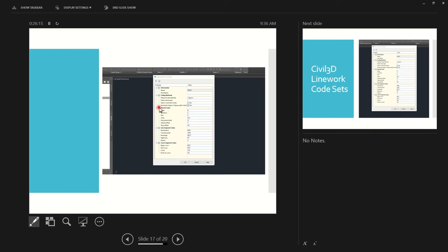But if I look at the special codes, this is for how it deals with line work, specifically lines. To begin a line, I have a B. That's why I was using B. To continue a line, I have a C. Say I ended a line by accident and I had another shot to take to continue that line on.